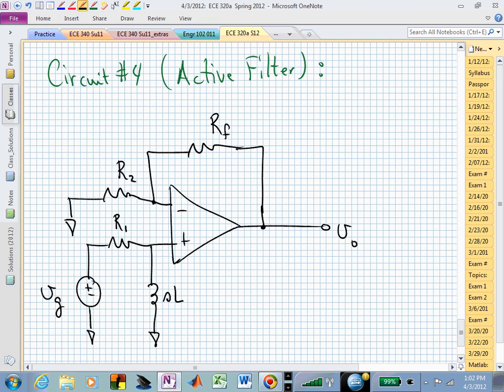Again, because we have this resistor in play, we do have negative feedback, which allows us now to make the same kinds of claims that we've been making all along. If somebody wanted to know what this current was, I sub P, what would you tell them? That's 0. And this current here, I sub N, is 0.